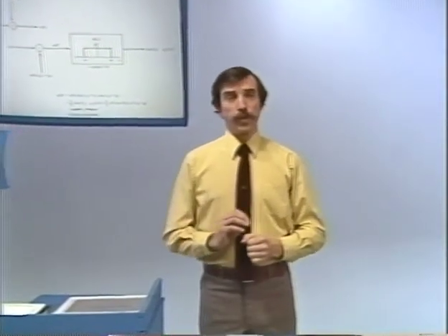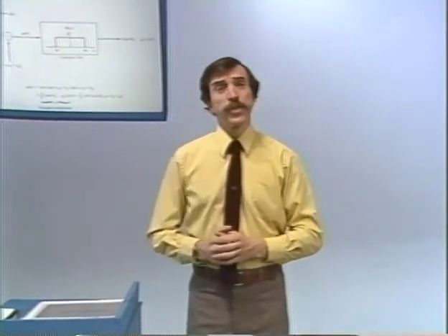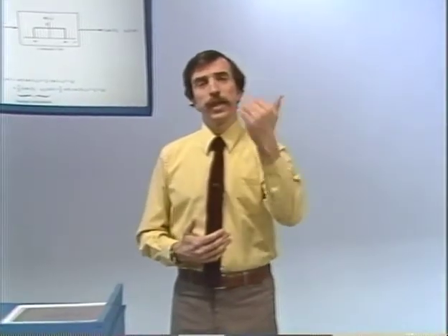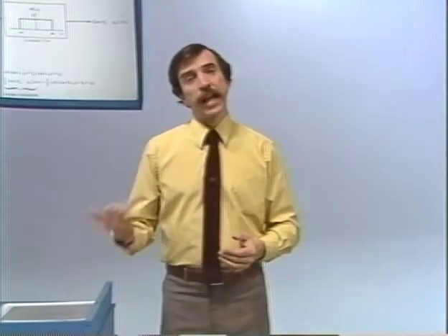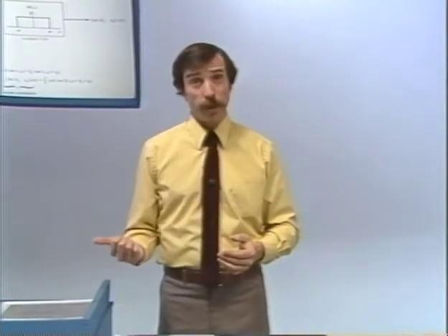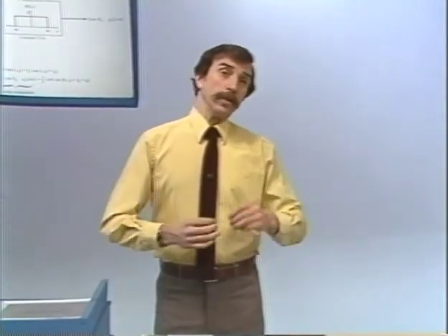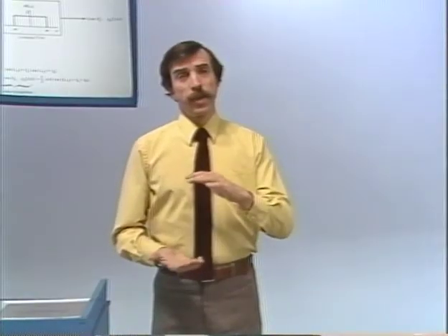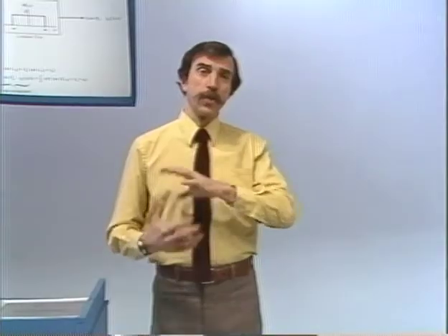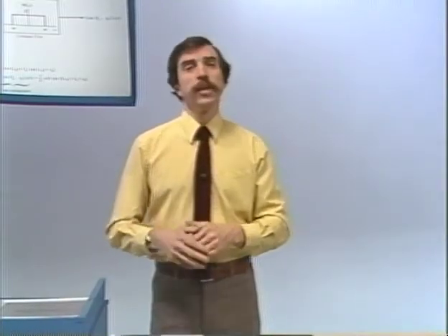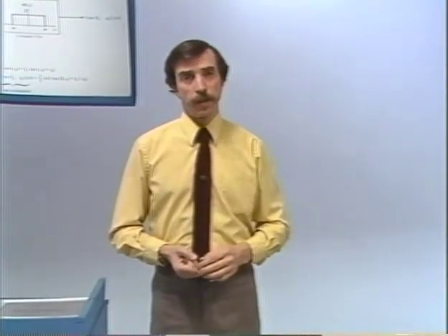But there are several points. One is, notice, for example, that if the phase difference between the modulator and demodulator is 90 degrees, then in fact the output of the demodulator is 0. Or if it isn't quite 90 degrees, the amplitude might be small, and the implication would be that if there's other noise that gets injected in the system, the signal-to-noise ratio is very low.